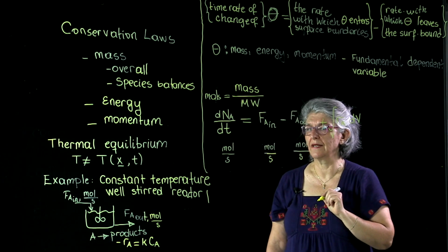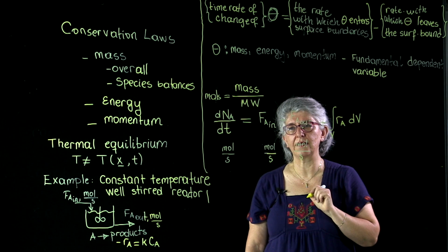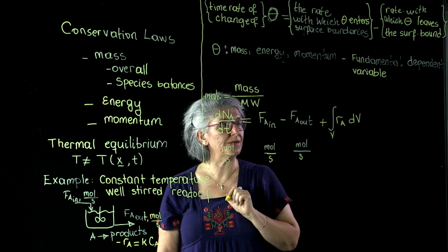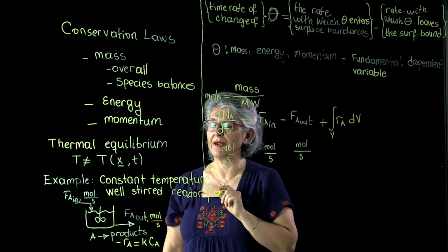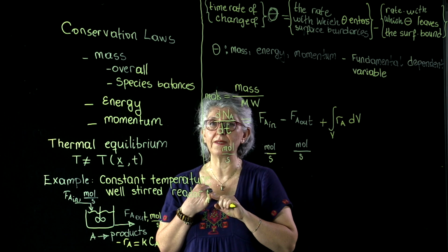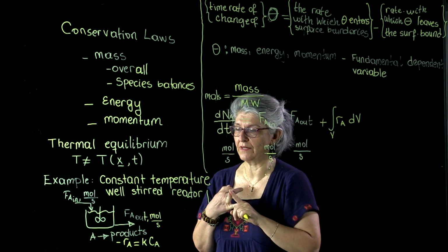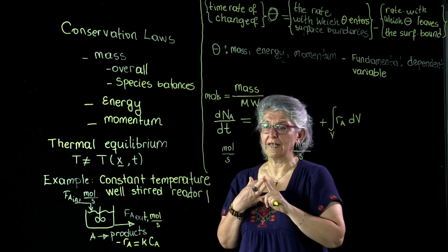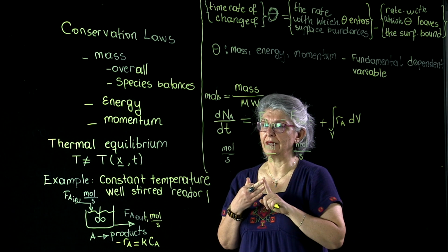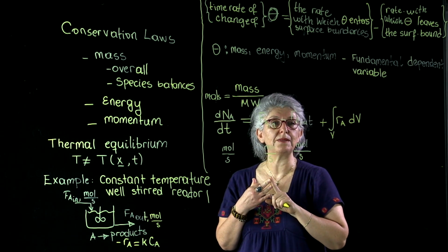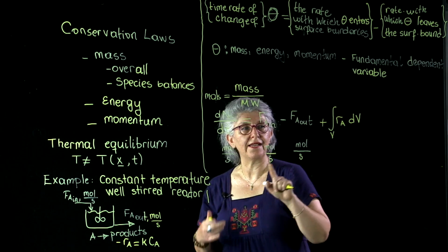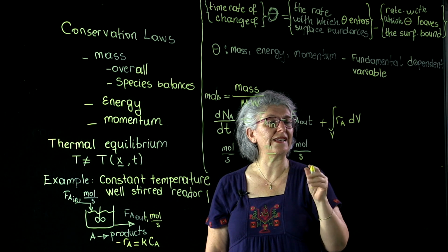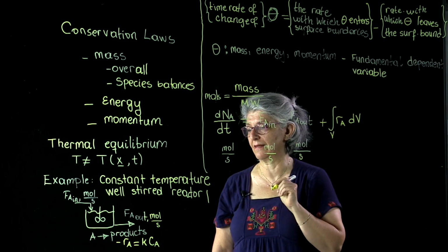The reason that I have put this equation in such an integral differential equation is because I have been telling you about the temperature non-uniformities, the concentration non-uniformities, and even inhomogeneities in the flow domain. And as such, I anticipate a non-uniformity in the reaction rate, and by integrating throughout the reactor volume, I obtain an average reaction rate.